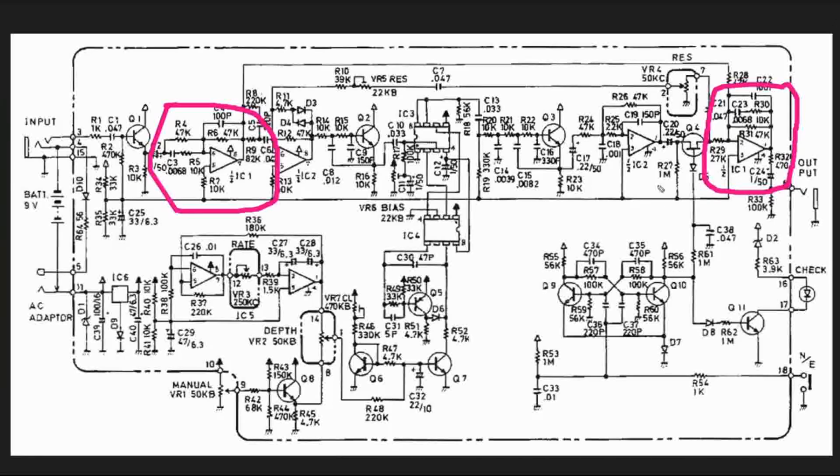So what we do is we undo it with this de-emphasis filter that actually is really just the inverse of this filter, so that if we were to stack just this filter and this filter, we would get a flat response. So that is the first thing that's happening with our output from this op-amp stage.